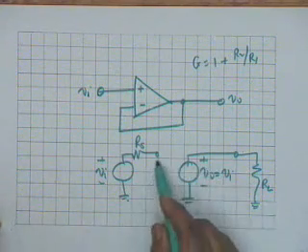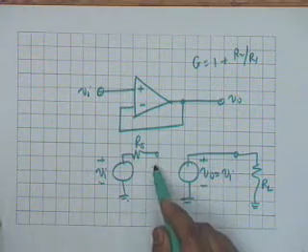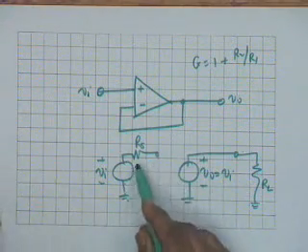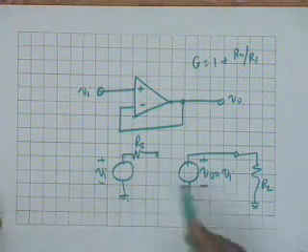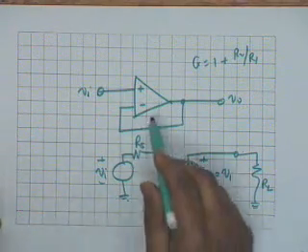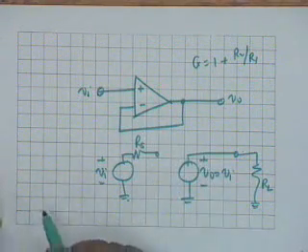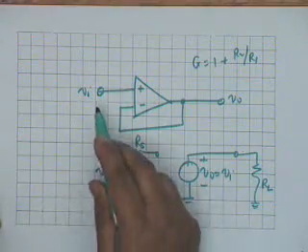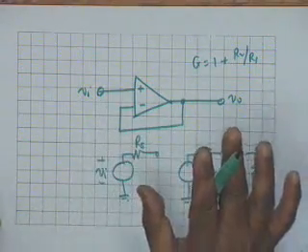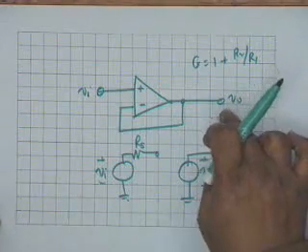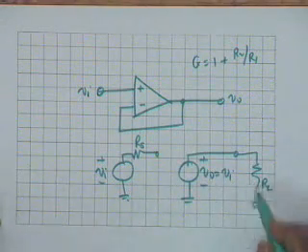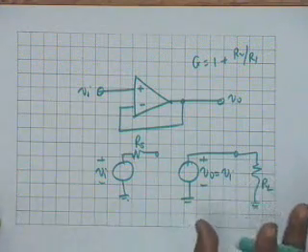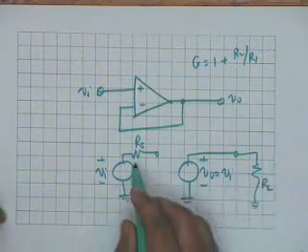In other words, the current in the load would depend on Rs, which is not the case here, because Vi, whatever the source impedance is, is transferred directly to the output, and therefore the load current or the load voltage shall remain Vi, irrespective of what Rs is.